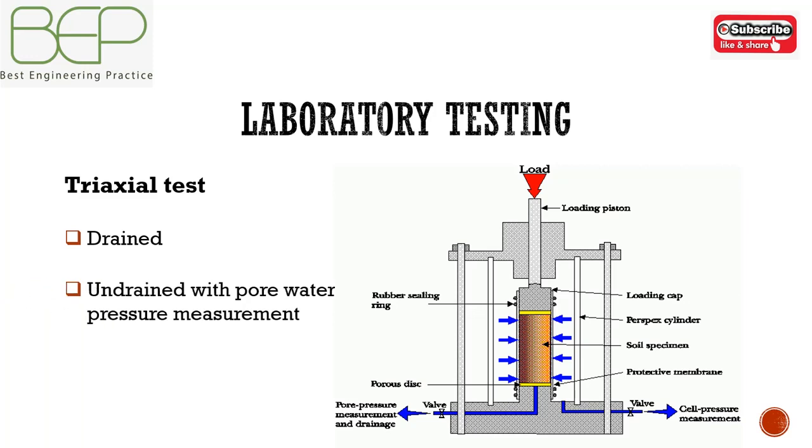Or undrained with pore water pressure measurement, where specimen drainage is prevented and the pore pressure in the specimen is measured during shear using a pore pressure transducer. Or undrained, where the vent is closed during shear, pore pressure is not measured and the test is interpreted in terms of total stress. Drained tests and undrained tests with pore water pressure are known as effective stress triaxial tests